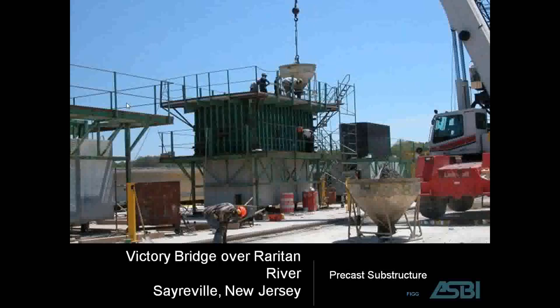Here we see the short line casting operation. This is a short line casting operation in the vertical orientation. The segment on the bottom is the match cast. The segment on the top is the wet cast. So after this wet cast is complete, and it's met its strength, it's lifted off because there's a bond breaker, once again, that's applied to the interface.